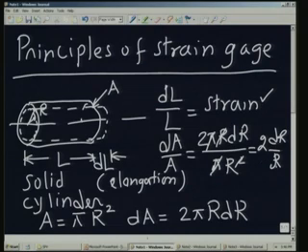and we know that dr by r is equal to Poisson ratio times dl by L, and therefore, I can write this as 2 times nu times epsilon. Epsilon L is the longitudinal strain, but I will avoid using the subscript, it is not necessary. So, I will just say epsilon.